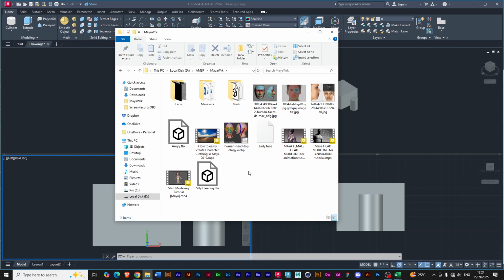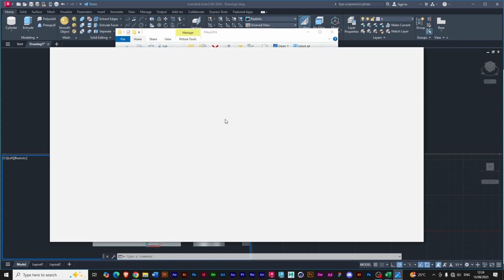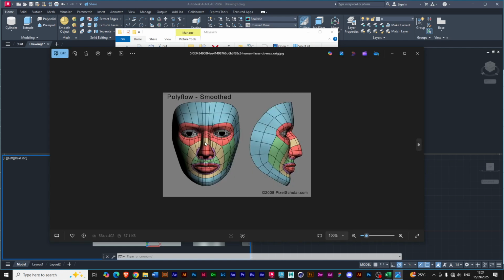So if you pick the wrong view to model that face, your model will become flat. So you have to know what view that person is facing. So looking at this model now, if that is the front facing side, right, this will be my right, but the object's left. And this will be my left, but the object's right. So looking at this from this view, it means I am standing on the object's right, looking towards the left. So this will be left view.